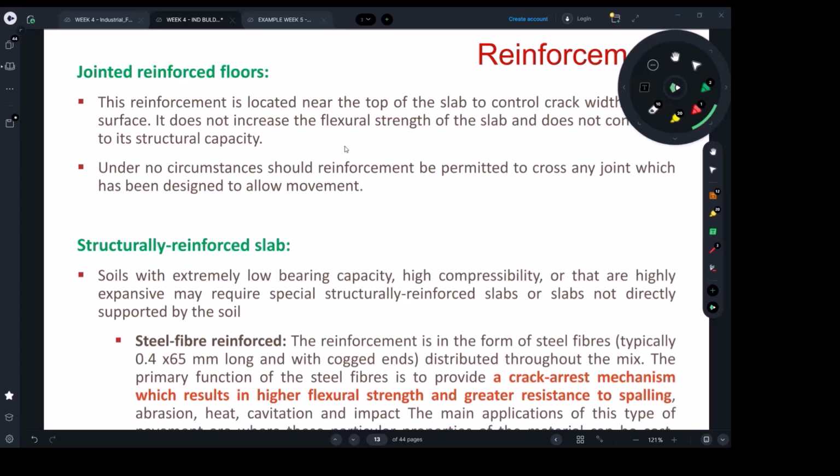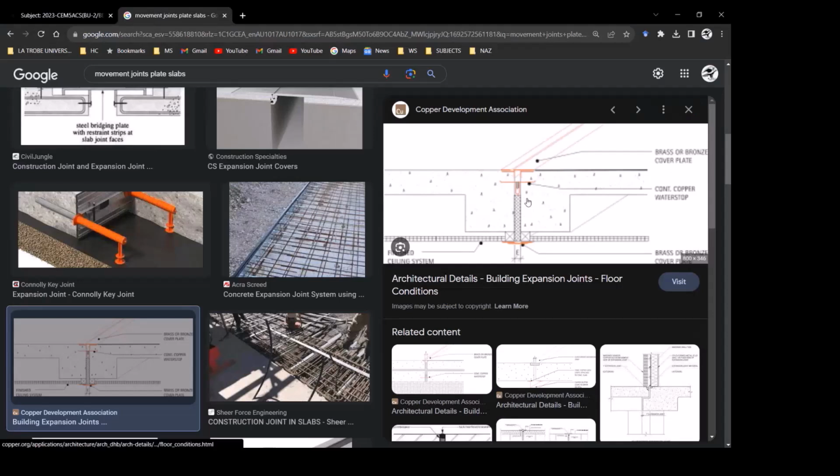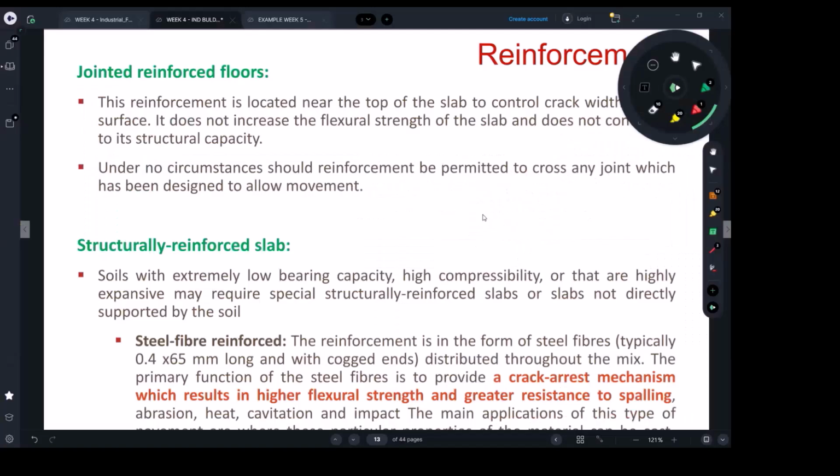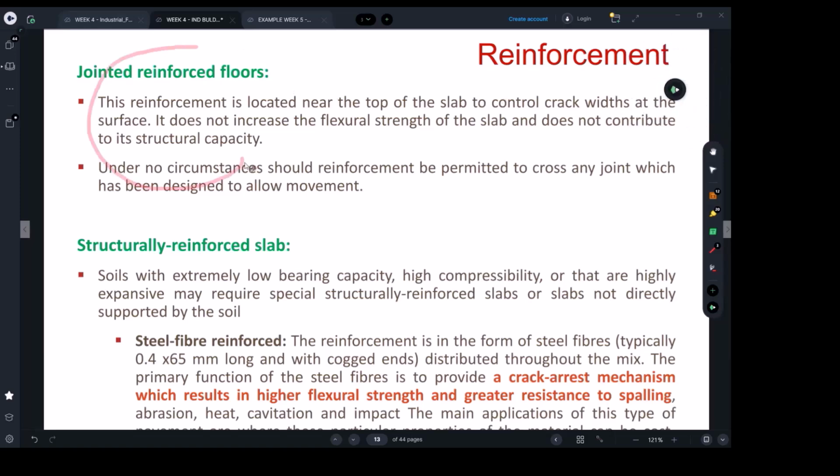You see them when you walk in any shopping center because they are very long. You're going to see these plates, and that means you cannot continue the slabs. You have to stop the pour and start another structure. If it was a construction joint, because the day is finished or it started raining, you have to stop the pour. With a construction joint, you can't continue the bars to lap together. We will talk more about joint types in the lecture, and you should know more about this.